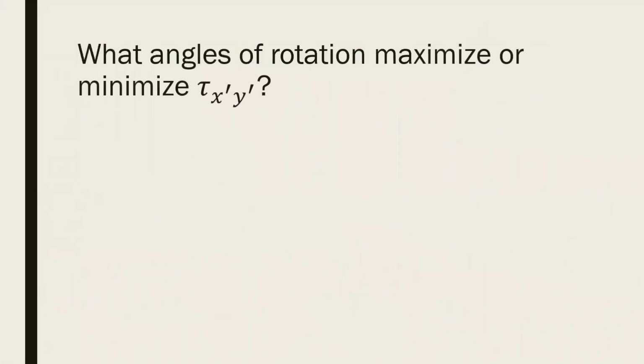Okay, so another big question we might be asking ourselves is what angles of rotation maximize or minimize the shear stress? How do you think we figured this out? Yeah, do the same thing, take the derivative, but now instead of taking the derivative of sigma x prime, we'll take the derivative of tau x prime y prime. Good.